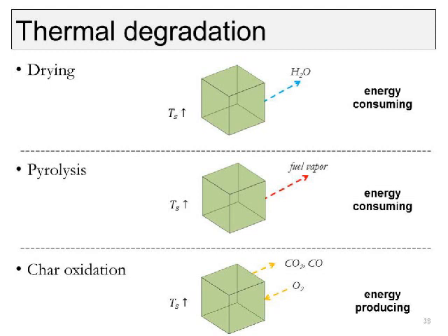That process generally ought to also consume some energy, and then we might have the development of some char. We raise the temperature further, and this can start to oxidize in smoldering combustion. We'll consume some oxygen and produce some CO and CO2, and also some energy. So these are the three main degradation processes that we want to capture in order to get our combustion and therefore our flame spread right.